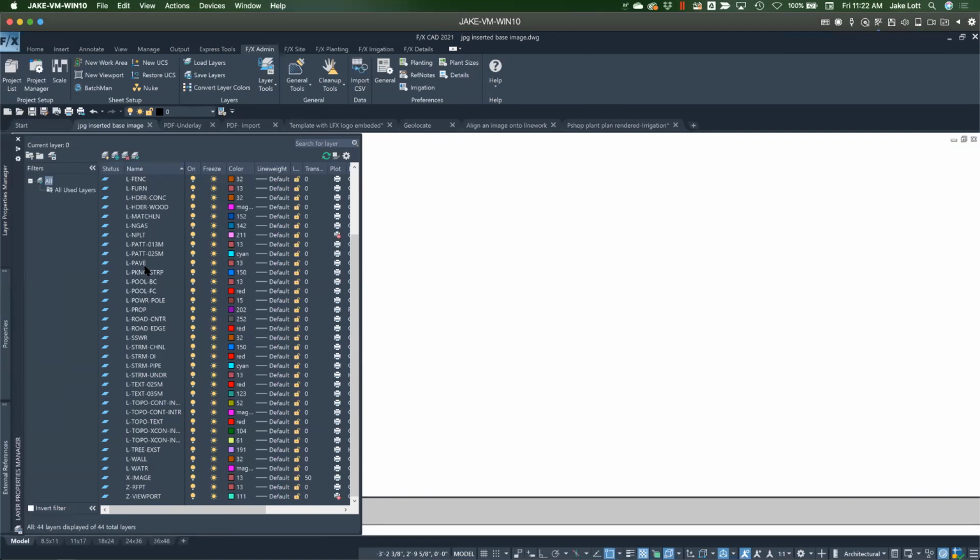And so I've made a consistent layer. I've got an XREF, and this is an image XREF. If I need to add an XREF and a PNG or a PDF or a geo located one, which we'll get into later, and have those be on a different layer, I'm going to do that. But I also want to set my transparency to something so I can actually see through it. And we'll get into that a little bit down the road here.